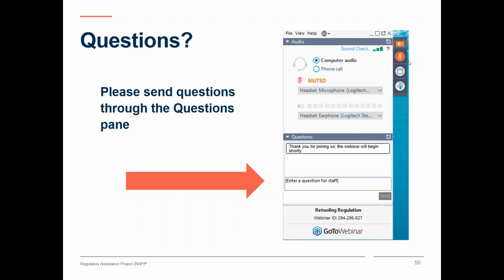And a more interesting application for AMI would be the fact that it jointly gives you the ability to provide some customer services like billing and disconnection, if you want to consider disconnection to be a service, remotely, but it also provides information that's useful for the distribution system and services that allow you to reduce line losses and improve power factor, and has value for the transmission and generation system as well.